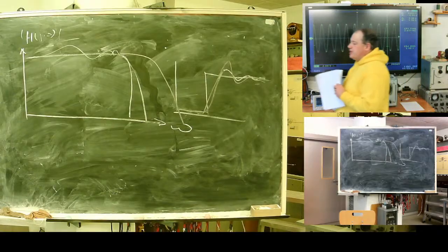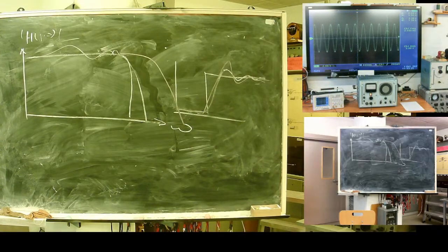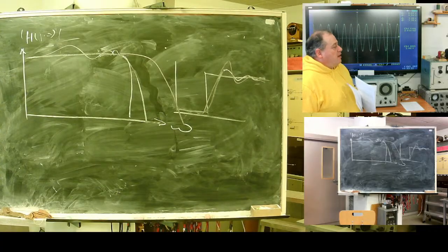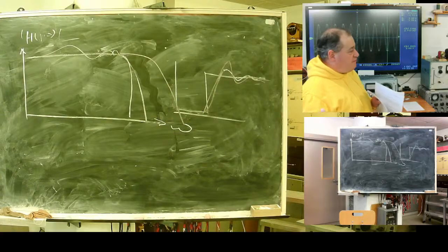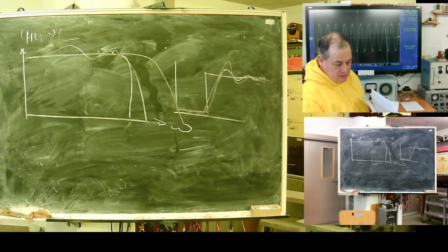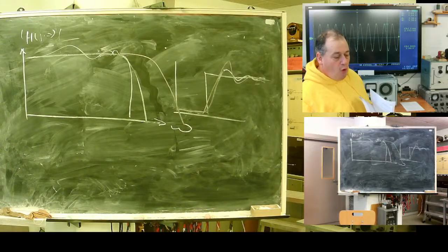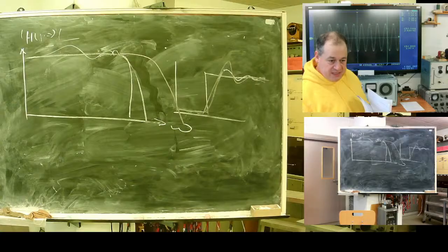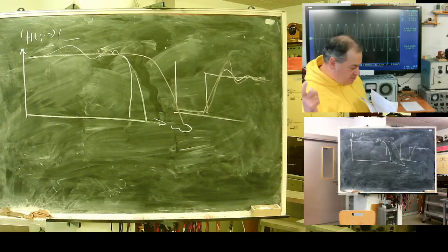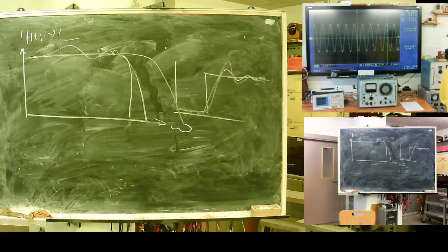Usually there is no silver bullet for filters. If you need good suppression of higher frequencies and you operate in a narrow frequency band, Chebyshev is good. If you need good performance on transients, Bessel is your choice. If you need uniform performance in a wider operation range, you look for Butterworth.